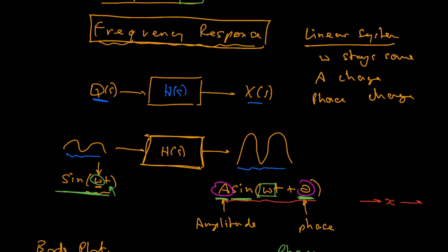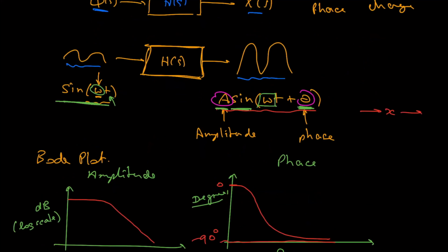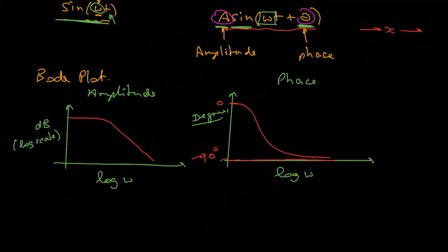You can imagine in an experiment, you'd inject a circuit with an input of a given frequency. You look at the sine wave that comes out, look at its amplitude, look at its phase, record those, and then try a new frequency and do the same thing. You can do this many times. If you do that, you end up with what we call Bode plots, from the person called Bode who introduced them. There are two Bode plots, one for the amplitude, one for the phase.